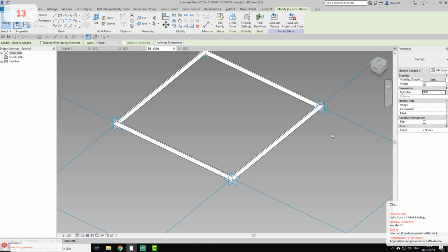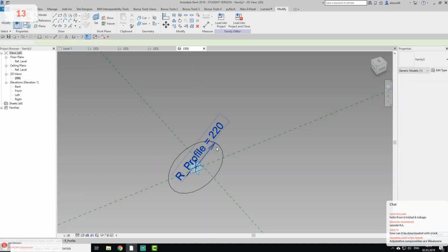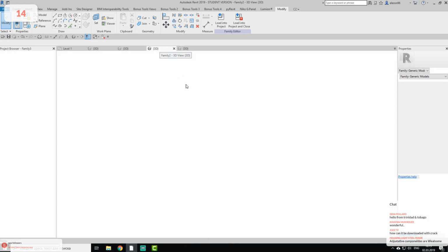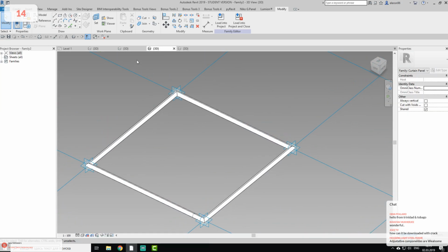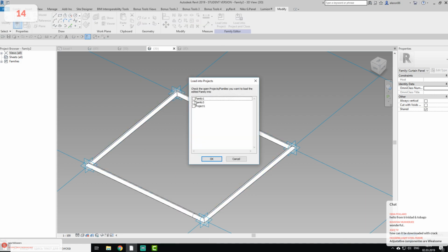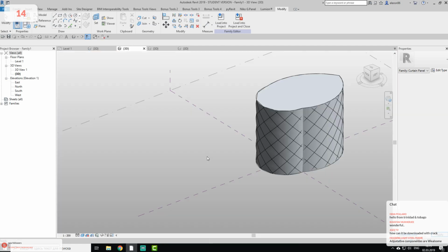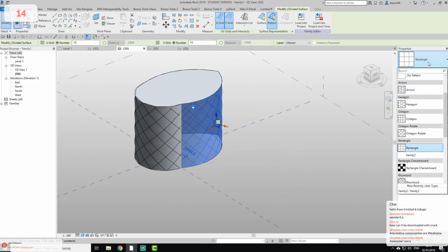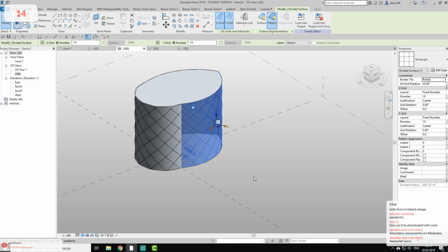And like this we are creating our family. For example, you can see, to create the profile, I'm creating one family with a dot. You have a lot of ways to create your profile, so I'm using this way to create this profile. After that, you load it into the pattern based family. After that, you load this pattern based family inside your family one, where your mesh is located. And after that, you change here to your family.